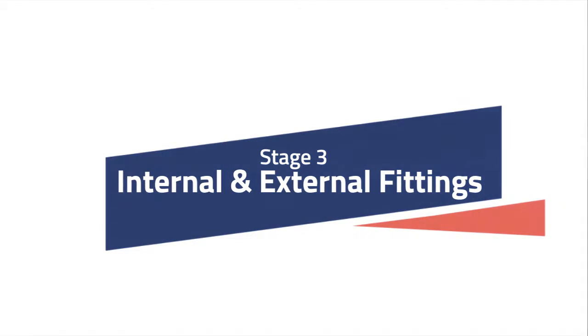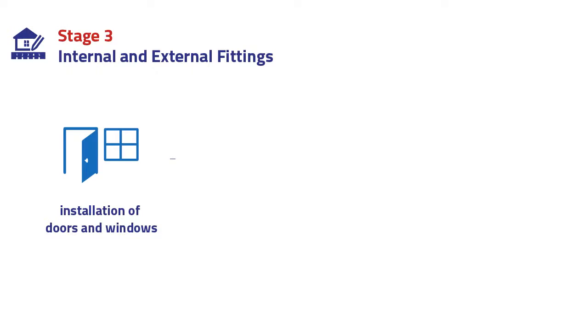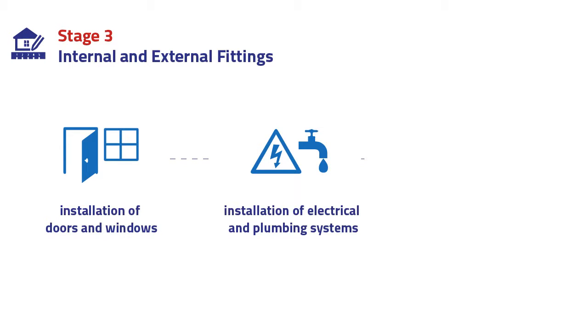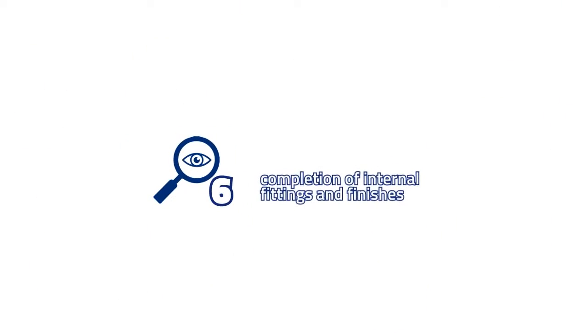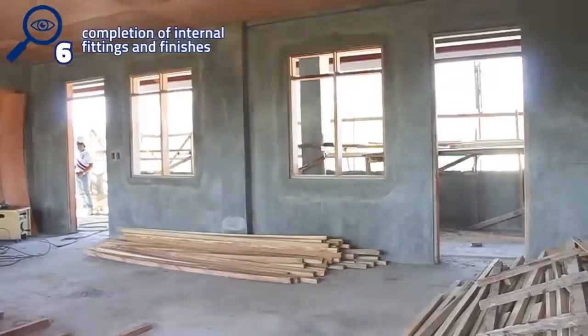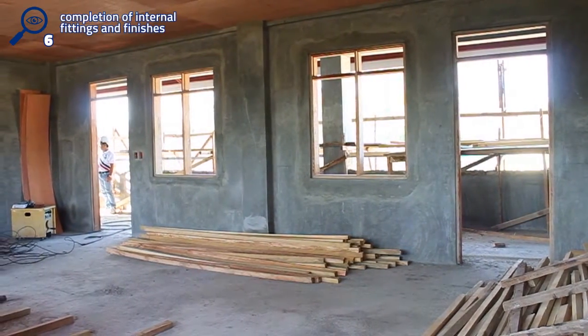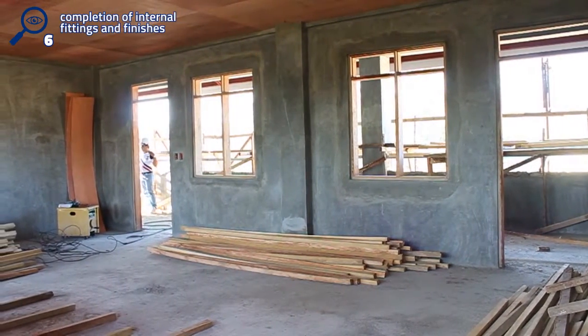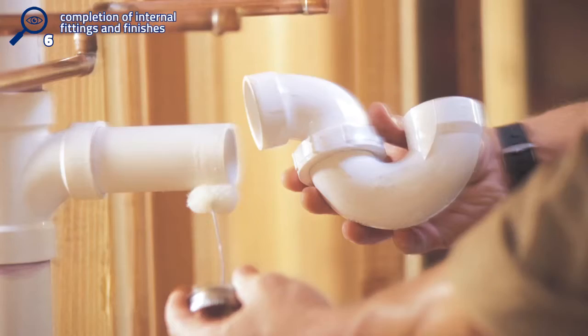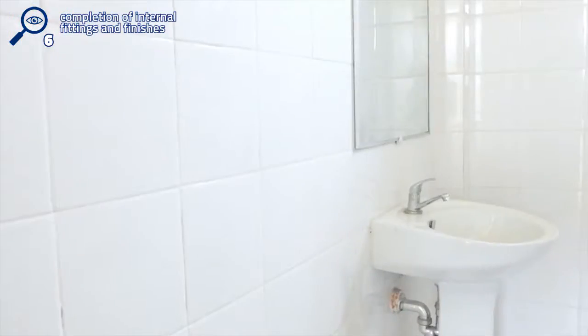Stage 3. Internal and external fittings. In this stage, the key activities are installation of doors and windows, installation of electrical and plumbing systems, painting and tiling works. There is one key inspection point during this stage of the construction process. Key inspection point 6. This inspection should take place once the contractor has completed the internal fittings and finishes, covering installation of doors and windows, installation of electrical and plumbing systems, and painting and tiling works.